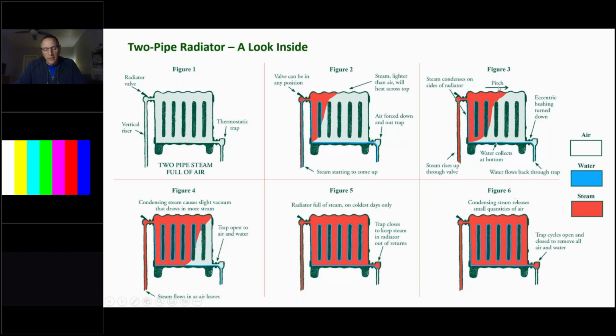Pitch is important here. Over a period of time, or if people have decided to remodel their rooms, sometimes they'll disconnect the radiator, lay a new floor, and then just repipe the radiator. You need to make sure that that radiator has some type of pitch. It doesn't have to be great. It just has to be pitched so that the water will flow towards the return side of the radiator. If it sits in there, you can get what's called water hammer, and we'll discuss that a little farther down.